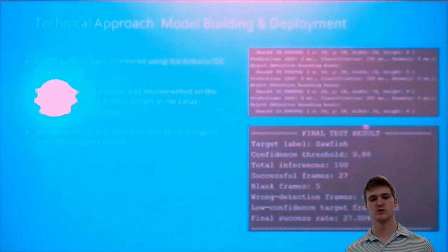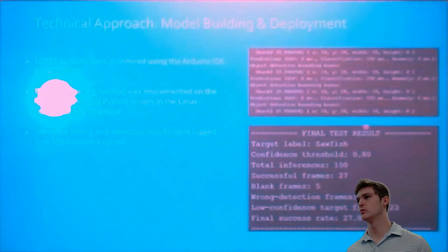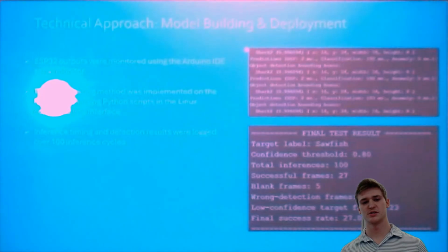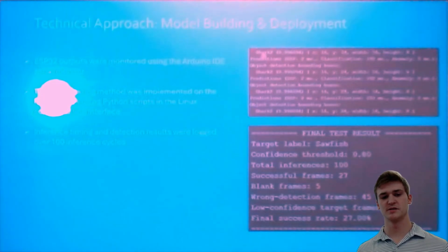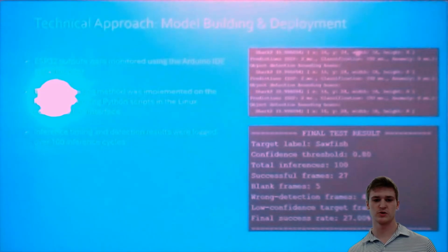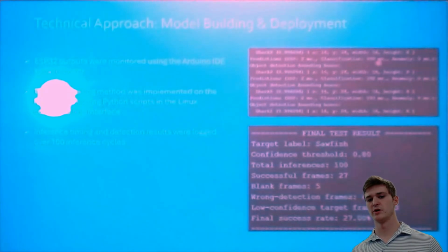Additionally, as well as the live view outputs, you can get these text-based outputs. This is within the Arduino IDE serial monitor. You can see the object detection model is saying that it's detecting the Shark 2 target with a 99% confidence rating, and it's outputting the location of the bounding box for the target, as well as the inferencing speed that I mentioned earlier, so 192 milliseconds.